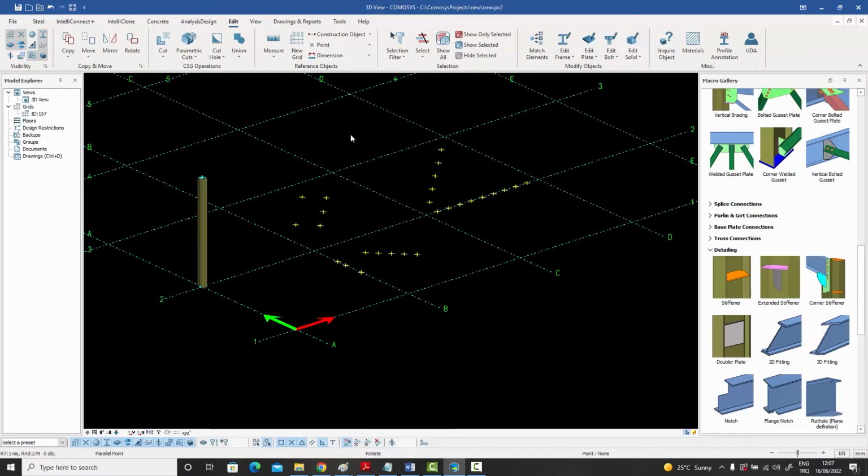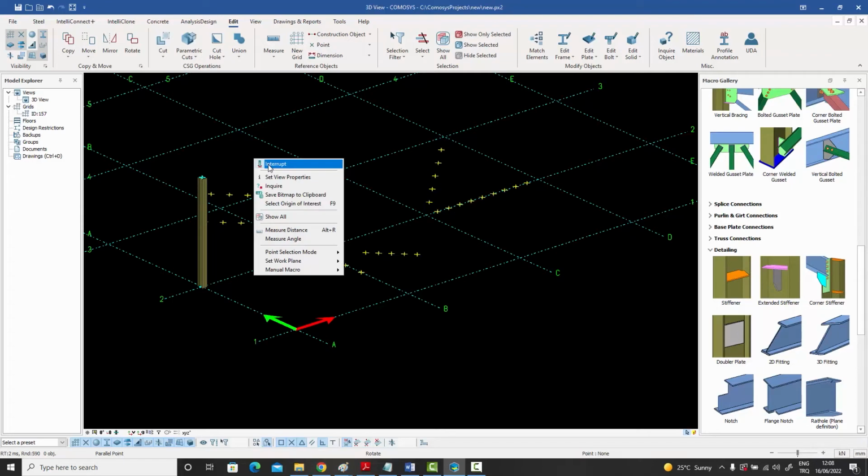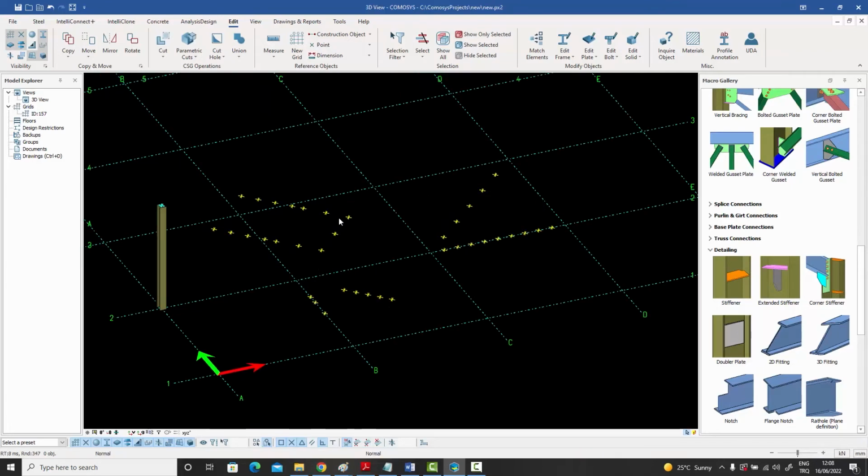Once again, over here, we can use that neat trick of saying 1000 space 500 space 3 into 750, for example. If I do that and I then select these 2 points, this time I'm going to get 1000, whatever number I said, 500, and then 3 into 750. So once again, using this trick, I can create multiple parallel points at variable distances.